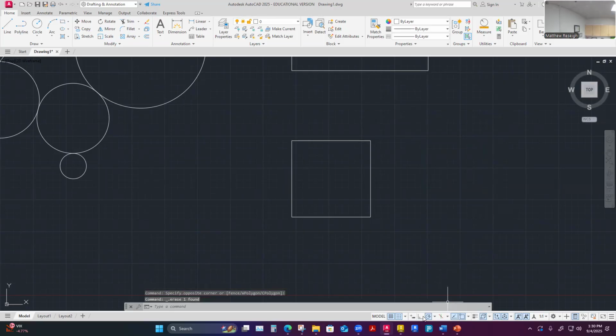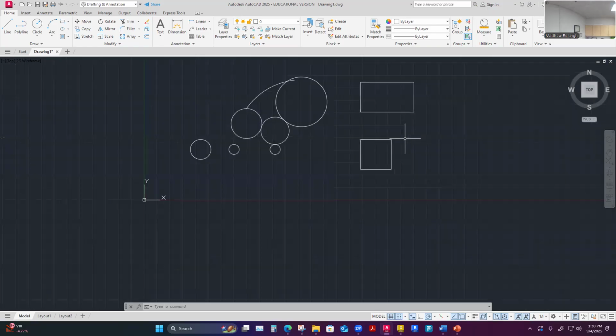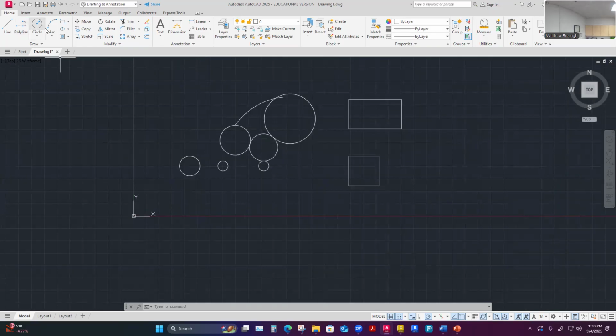So I mostly keep my dynamic input on all the time because I do a lot of the units input while I'm in the command. I'm generally inputting a dimension for whatever I'm drawing in most situations. So, okay, excellent. What else we got?